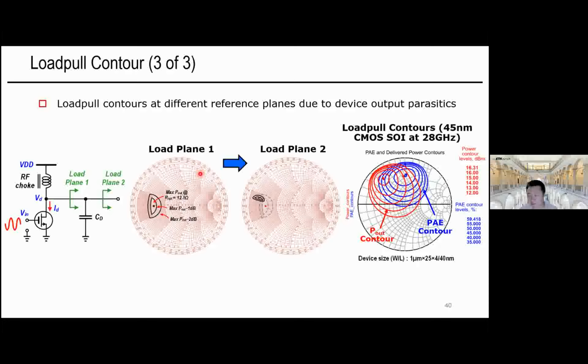It really depends on the input. So again, this goes back to what kind of PA you are designing. If you are designing a normal class A PA, then the input voltage or power level also depends on what kind of driver you can have, the breakdown of the driver, and the supply voltage limitations too. With that consideration, you can more or less understand what the maximum input voltage drive is. Based on that, you can design the input drive, and then you can design the optimum gamma L.